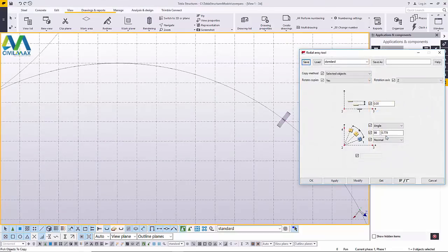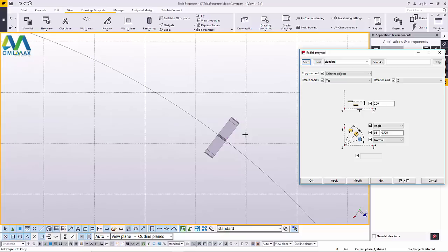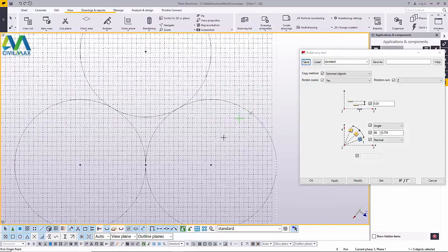We'll double click on the radial array tool, and we'll pick the shells first, because we want to populate these shells along the path we've just defined. We'll click on that and press Ctrl and pick on this, then press our middle button on the mouse, and we'll go straight to the midpoint here.